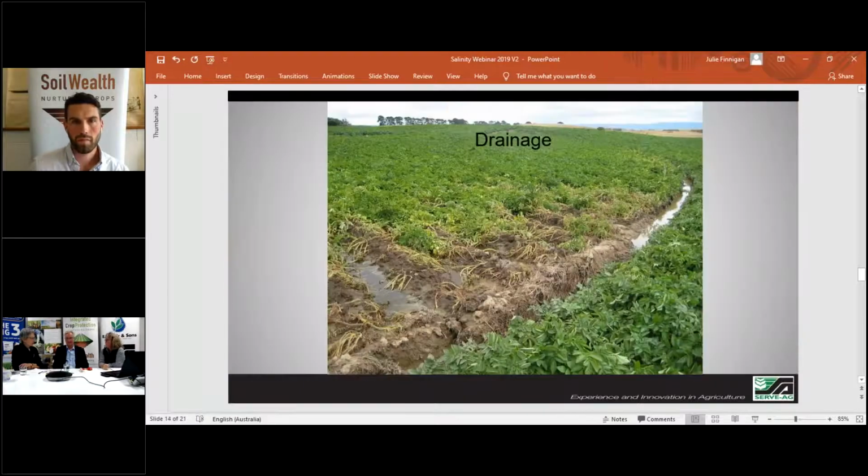I found that it was sometimes difficult to get the calibration solution. So it's probably a matter of pestering the people who supply it. That's right, and you can buy the calibration solutions to do that. But again, make sure it's kept in the right environment as well. So don't have this sitting in the car in the heat and then try and calibrate it. Leave it in the office where it's more stable and do your calibrations there.